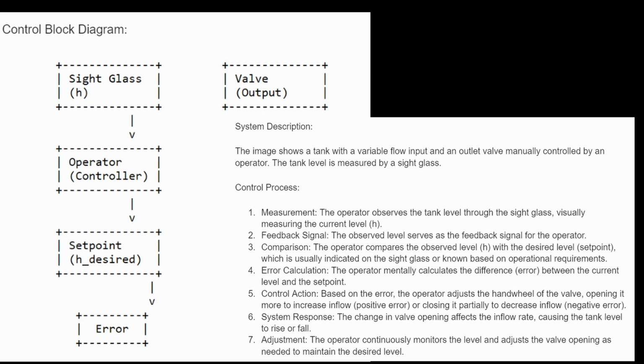6. System response. The change in valve opening affects the inflow rate, causing the tank level to rise or fall. 7. Adjustment. The operator continuously monitors the level and adjusts the valve opening as needed to maintain the desired level.